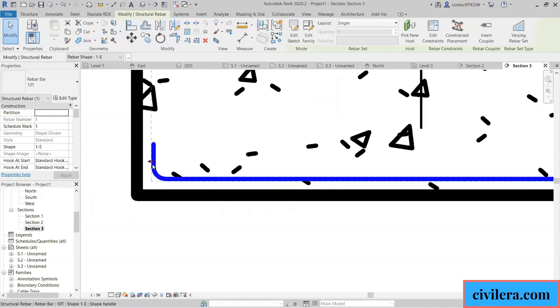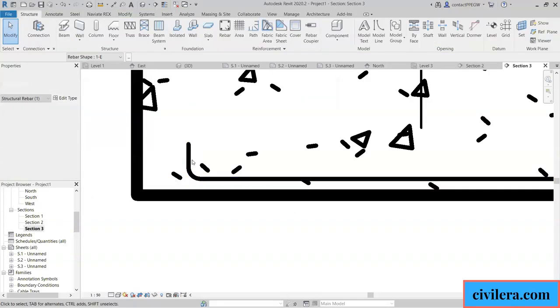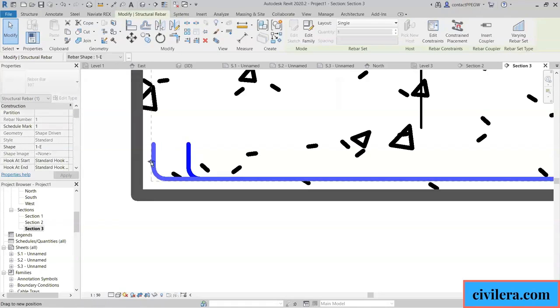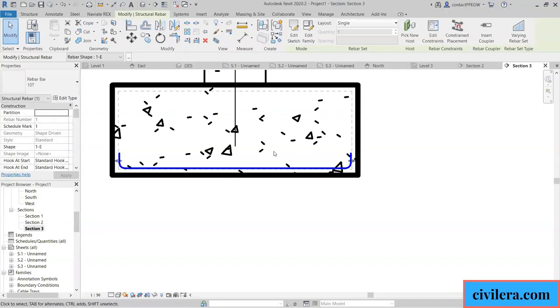Yeah, you can do that. Now, if you want to move it in this manner, it's very easy. You can do this. Now, click on this and you can decide how many numbers, fixed numbers or maximum spacing or number with spacing, whatever you want to. So I'm going to choose maximum spacing because now it's only one bar that we have placed. I'm going to say maximum spacing and then say my spacing is say 100 or 200. So now you have 10 at 200 in that particular